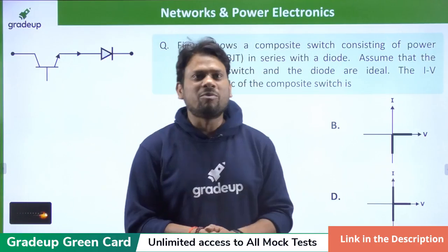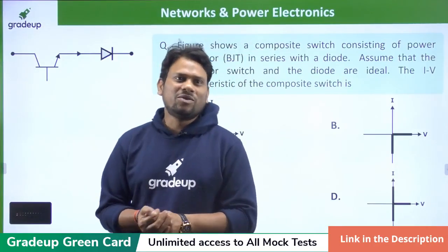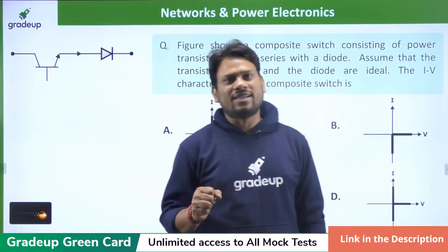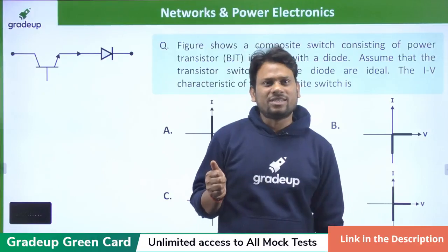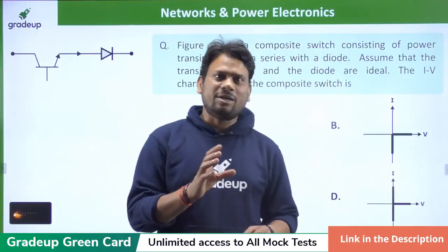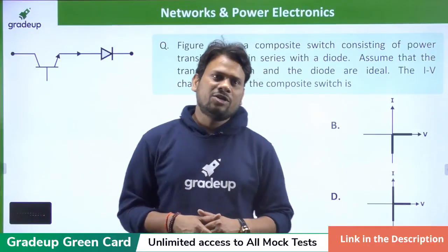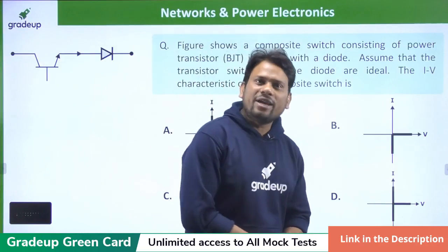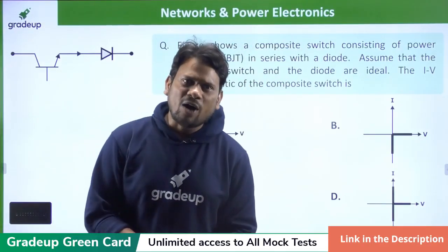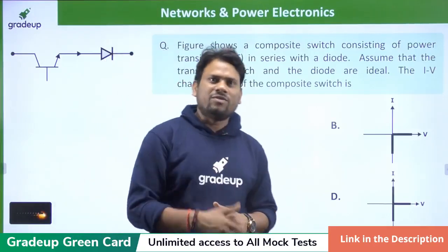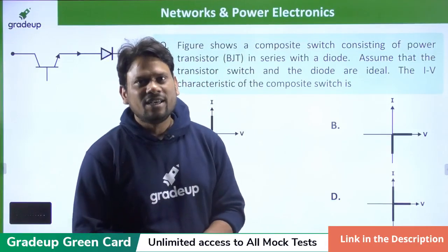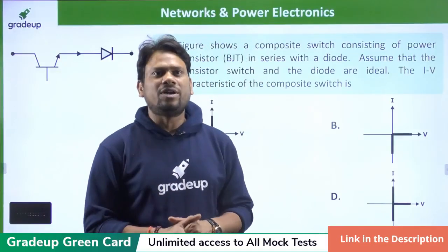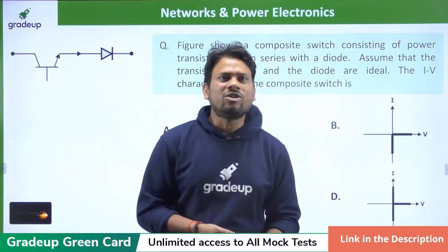What is the difference between harmonics and noise? Anas Khan. Okay. Anas, due to harmonics, noise is introduced; due to harmonics, power factor decreases; due to harmonics, efficiency reduces. So when harmonics or any interrupted signal are present, then noise will be introduced. So noise is born due to harmonic components. For example, when we operate our load by an inverter in a domestic field, in our home, then due to inverter conversion, DC to AC, some harmonics are present at the output of the inverter. Due to that harmonic, fan, tube light, and inductive load produce some sound. Okay, so this applies to mechanical also.